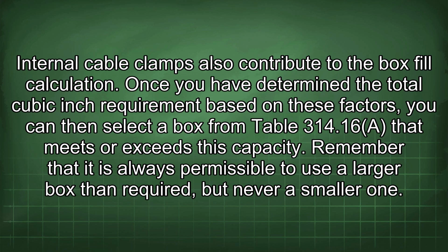Once you have determined the total cubic inch requirement based on these factors, you can then select a box from Table 314.16 that meets or exceeds this capacity. Remember that it is always permissible to use a larger box than required, but never a smaller one.